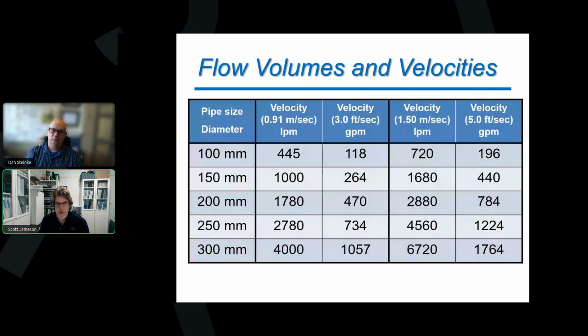So, once again, let's say we've got a 10-inch main there, and we've got to get those very high flows. Well, then you might look at going out of the 4-inch port. And they do make equipment for diffusers that will go off a 4-inch port. But really, for anything up to, I'd say, an 8-inch pipe, just flushing out of a 2.5-inch port should be sufficient for you, depending on your system pressure.